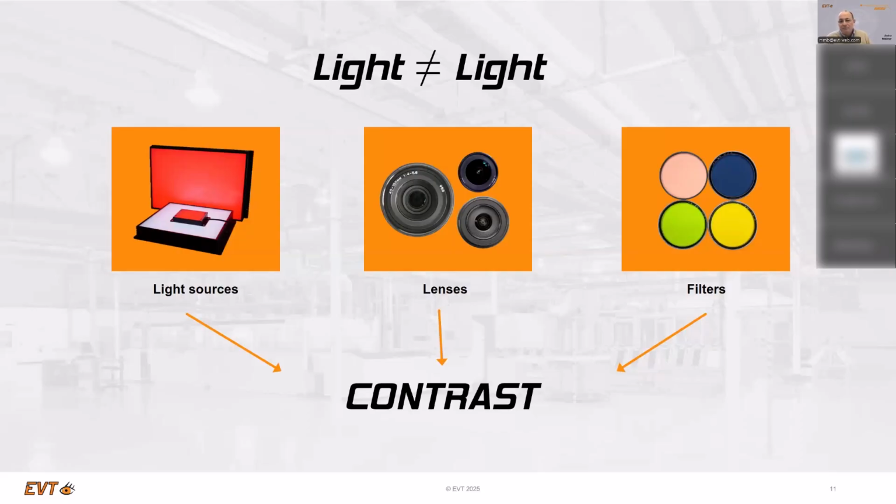First of all, the worker at the machine cannot see the UV light, and based on that, he is not disturbed by the flashing UV light. And finally, for the camera, it generates a very good contrast anyway, because you eliminate the daylight which is necessary for the worker, but if these wavelengths are cut, the camera doesn't see it. So you don't get reflections from a ceiling light or whatever. You simply see the flashlight which you have installed.